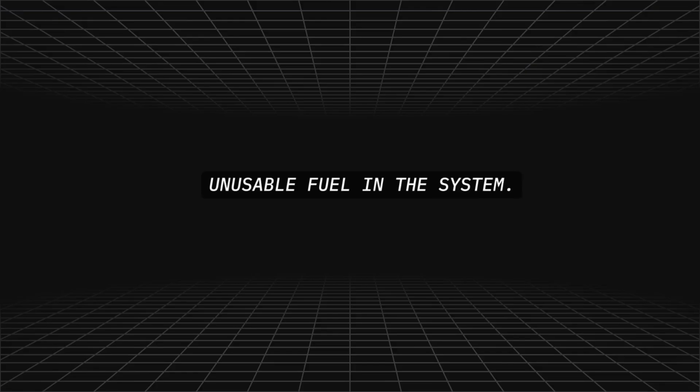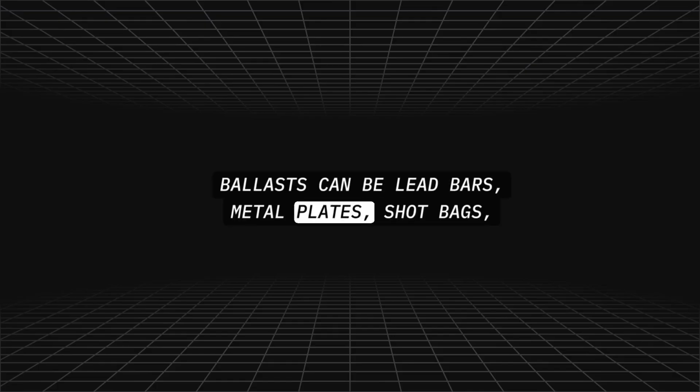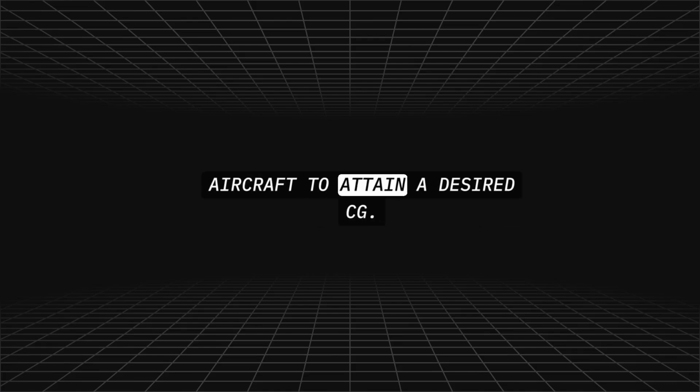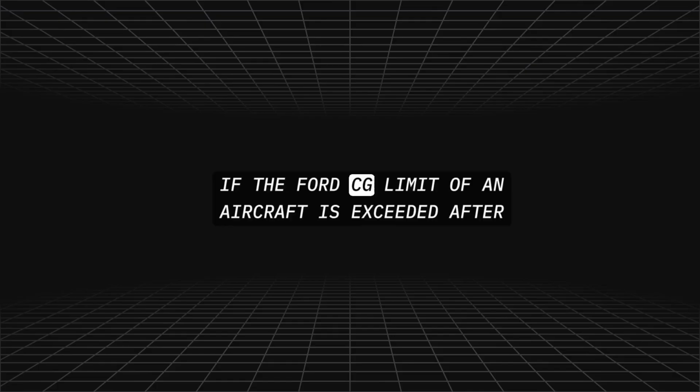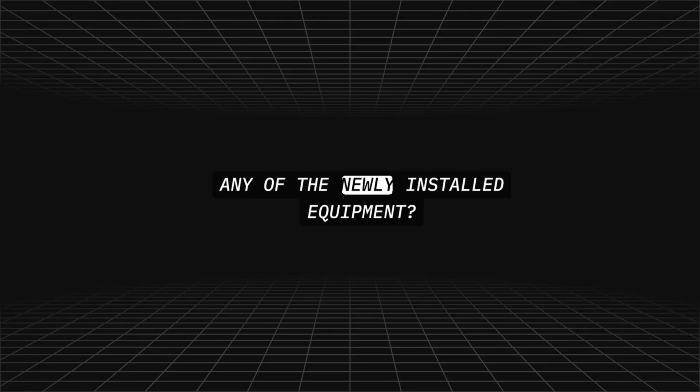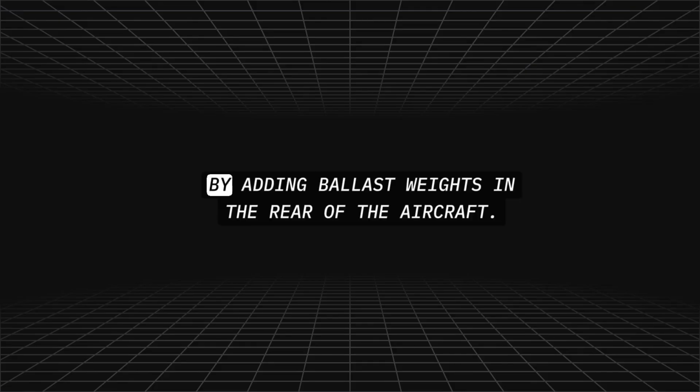What is ballast? Ballast can be lead bars, metal plates, shot bags, sandbags, or other items of weight which are placed in the aircraft to attain a desired CG. If the forward CG limit of an aircraft is exceeded after installing several items in the engine compartment, how could the CG be returned to limits without removing or changing any of the newly installed equipment? By adding ballast weights in the rear of the aircraft.